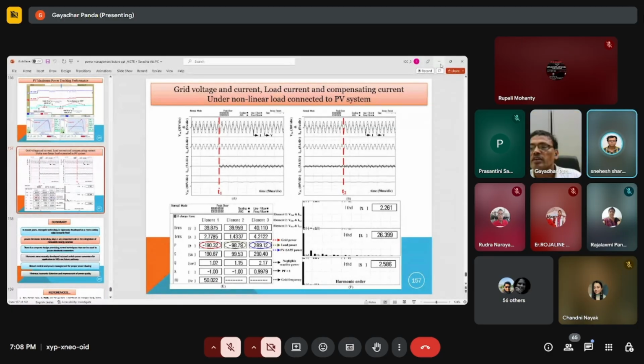I have a question about SPWM inverter. You have just discussed the mitigation technique of harmonics in SPWM inverter. So my question is, what is the best technique, third harmonic injection or selective harmonic elimination, which will give us the optimal result in case of harmonic elimination?